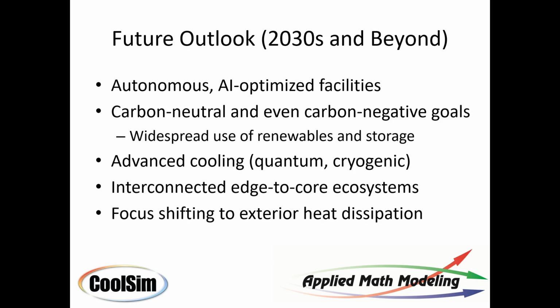The issue of cascading hot air coming into the intake of downstream chillers is becoming more of an issue as densities rise, because there's just so much heat coming out of a data center. Being able to dissipate it across an environment, an atmosphere, given the specific location and wind condition, is becoming challenging, and we see quite a bit of work in the field of modeling, CFD modeling, to optimize the dissipation of heat into the atmosphere.